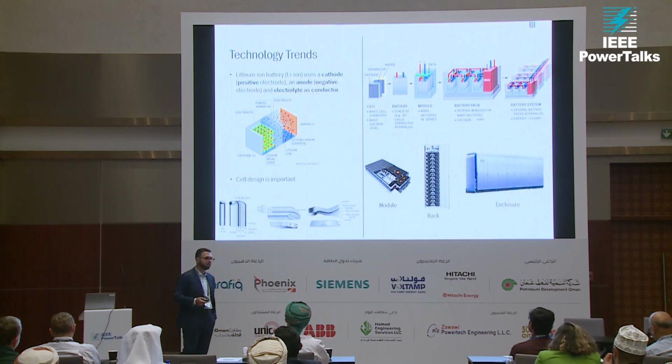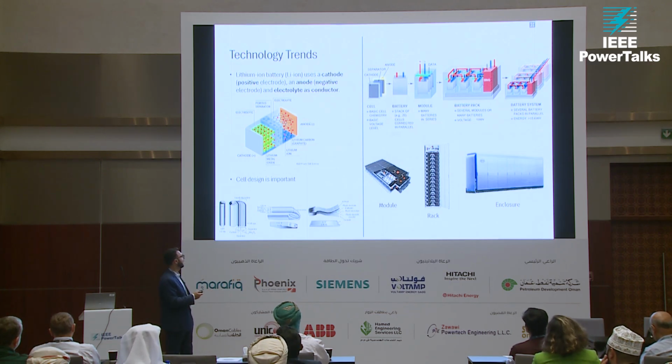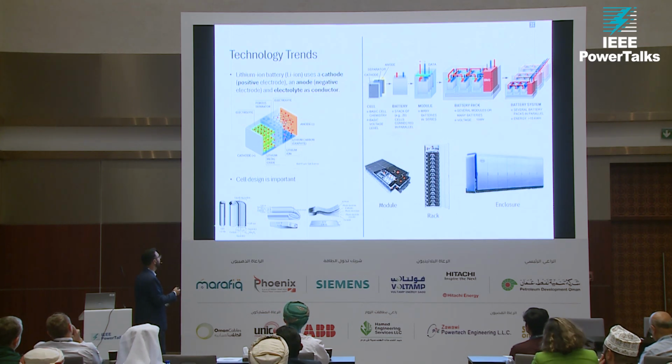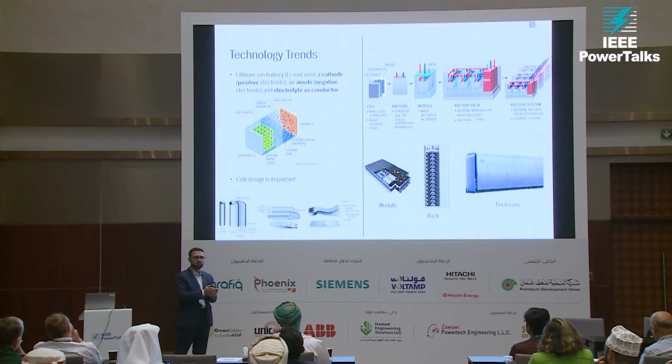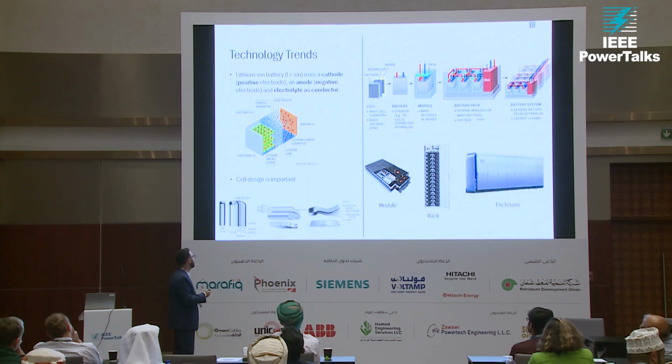Pouch is an older technology mainly used for NMC, and it's all about stacking sheets of cathode and anode and separator on top of each other. This is actually rolling those sheets together. This is a lot more dense. This is a lot less dense. This has an issue of expanding and contracting. So a pouch is basically a bag. It expands when you're charging it, and it contracts when you discharge it, which I've seen cause a lot of cracking on these cells.